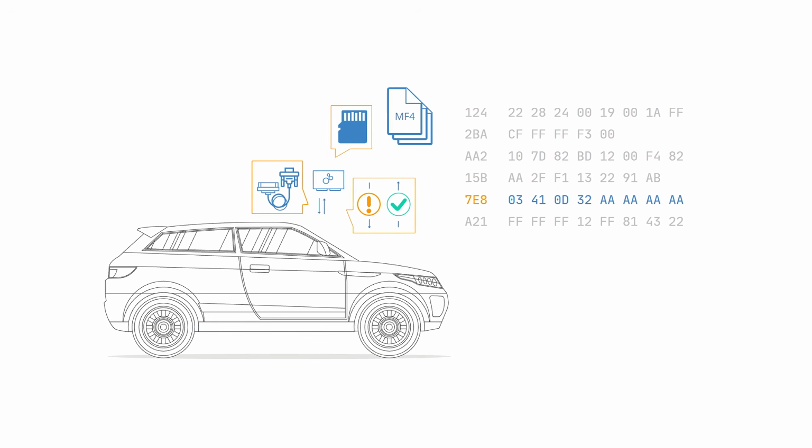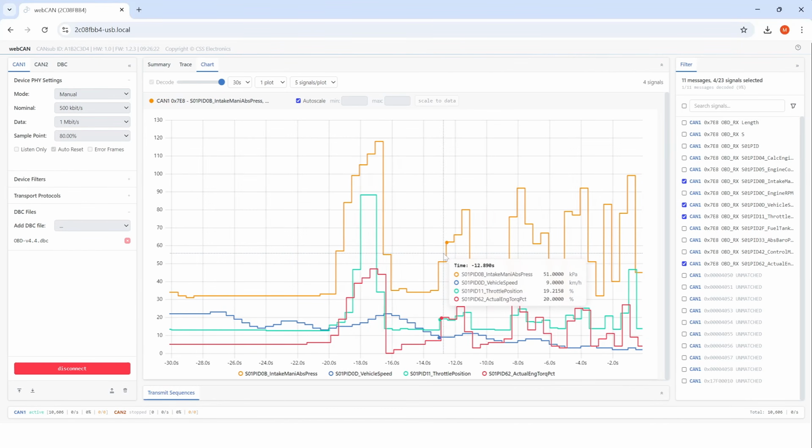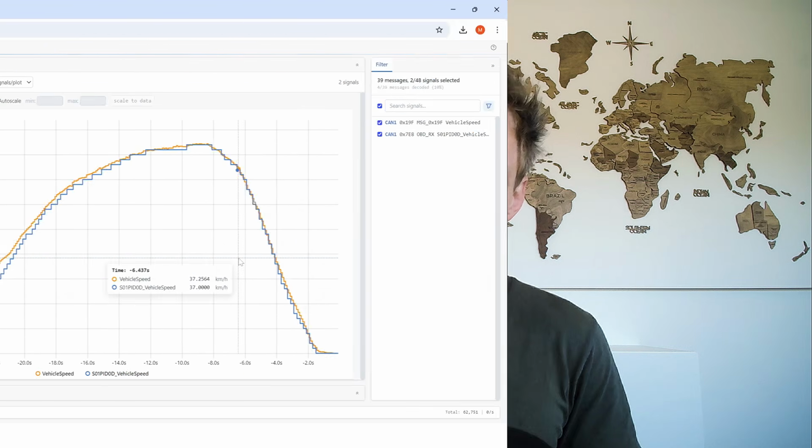And in a similar way, if you have your own car, and if we're talking a non-electric car, you can typically get some data through OBD2 requests, essentially asking the car to provide you with speed, RPM, and some other parameters. But what you're getting is essentially the discount version of what is available on the CAN bus. You are only getting a light subset, in this case, through OBD2. So if you want specific signals, or if you want the more rich data that is being communicated in your car, you essentially need to reverse engineer that information. And that's the exercise that we'll go through today.